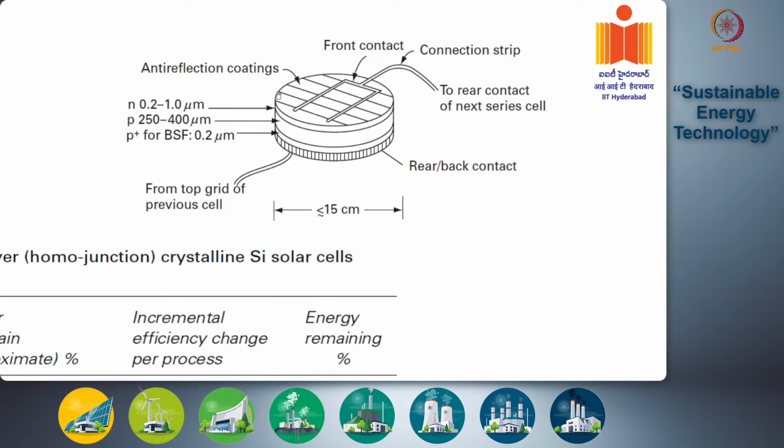that are basically very thin rods that are collecting all the electrons and delivering them to the front contact system. Below these rods, you have the anti-reflection coating, which is stopping the solar light from being reflected from the top surface of your solar cell.